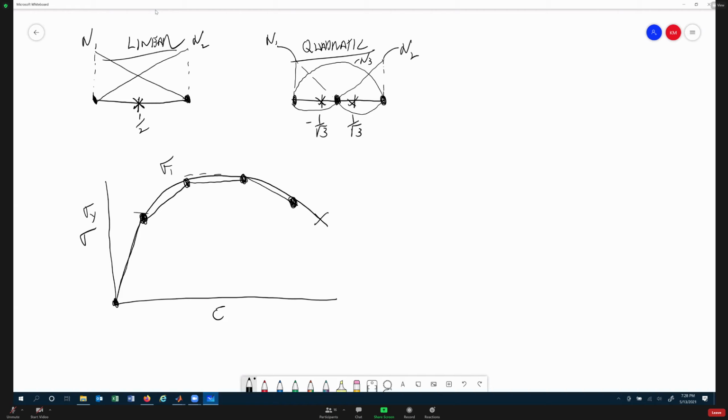So in this first one here, we've broken this up into 1, 2, 3, 4 segments. We're saying, okay, we're going to linearize this problem using 4 segments or 4 elements, if you will. And that's going to give me a certain agreement. But you could do the same thing using a quadratic. You could say, I'm going to break it up into 4 elements, but I want each one of these elements, instead of being a linear line segment, to be quadratic and fit to this function.